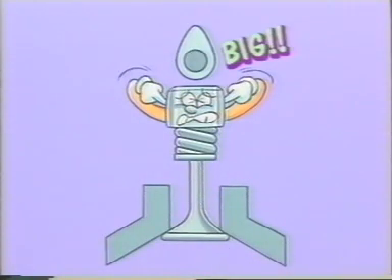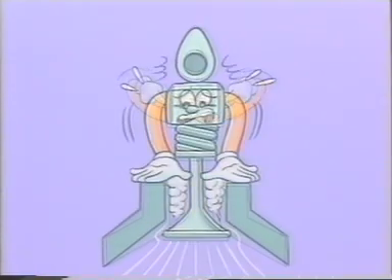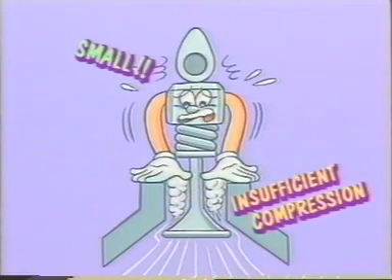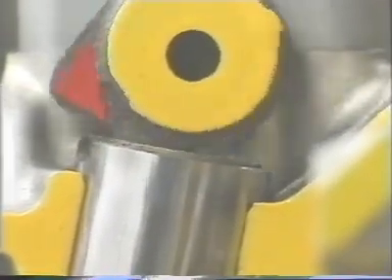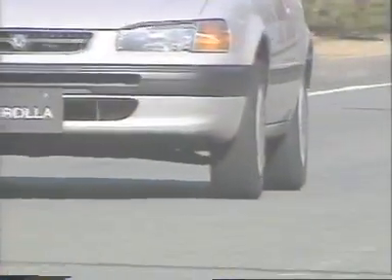Excessive valve clearance causes abnormal noise and improper valve operation timing. Insufficient valve clearance causes incomplete valve closure, resulting in insufficient compression. The valve clearance must be adjusted to an appropriate value. The valve clearance in a cold state is different from that in a hot state, as the valve clearance is affected by temperature.